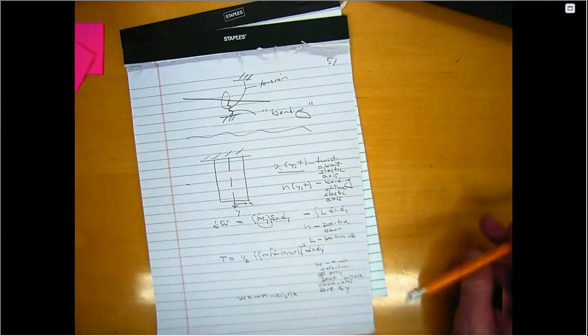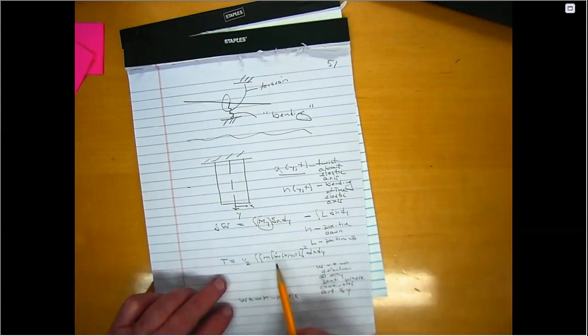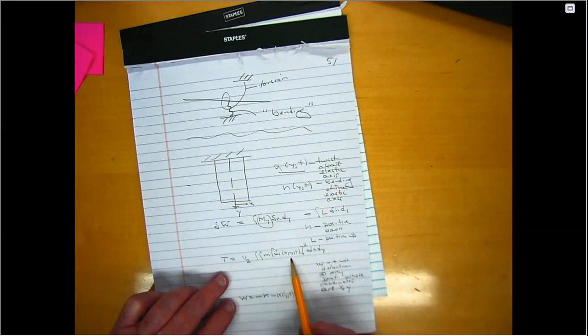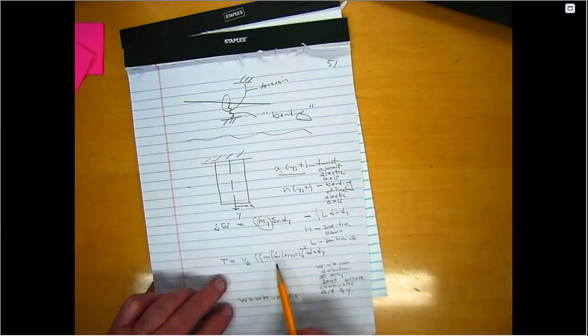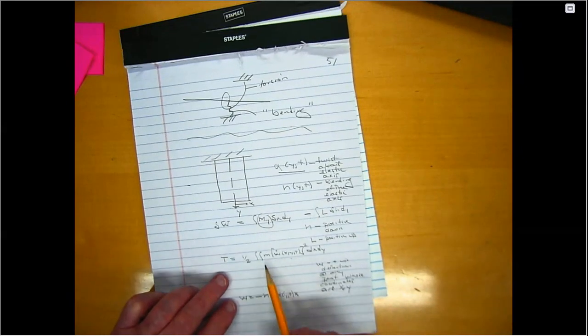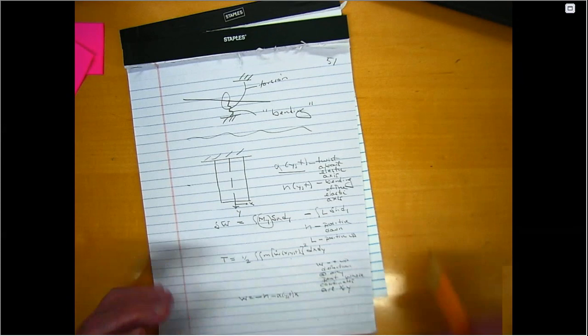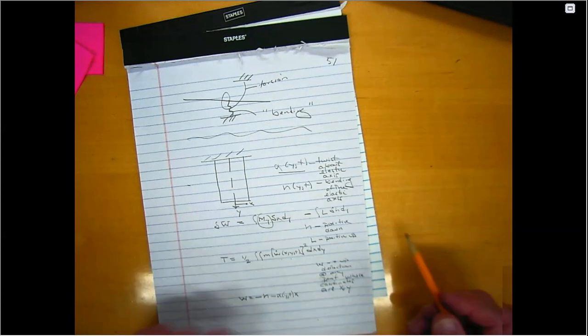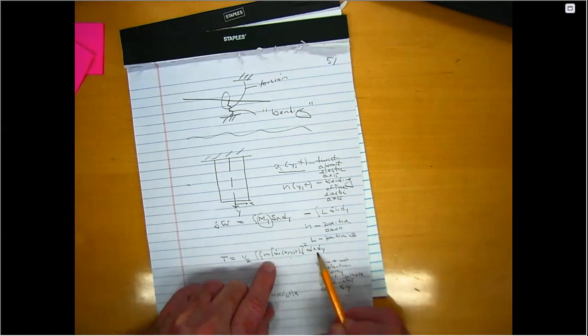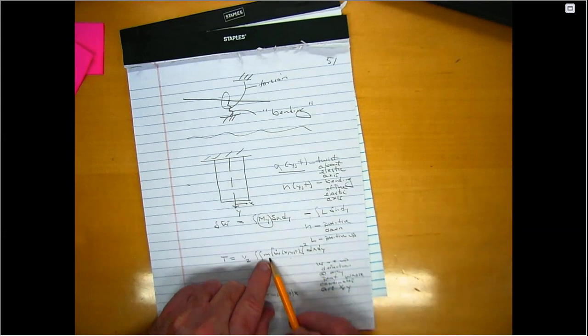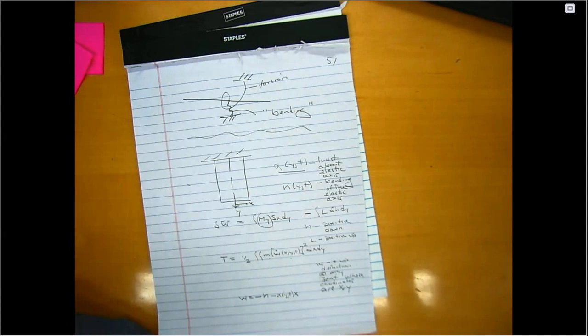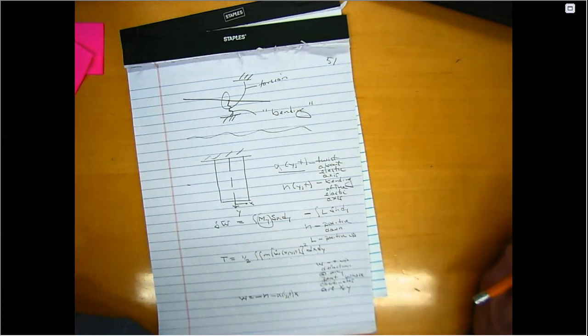Well, I'm pointing out that to get the kinetic energy, I went back to earth, fire, wind, and water. I went back to the basics. Kinetic energy is always 1/2 the mass times velocity squared. And if this is mass per unit area, then I need to integrate over the area. So I can think of this mass per unit area as what? If this is a solid wing, this is the material times the thickness. That's what it would be, the mass per unit area.